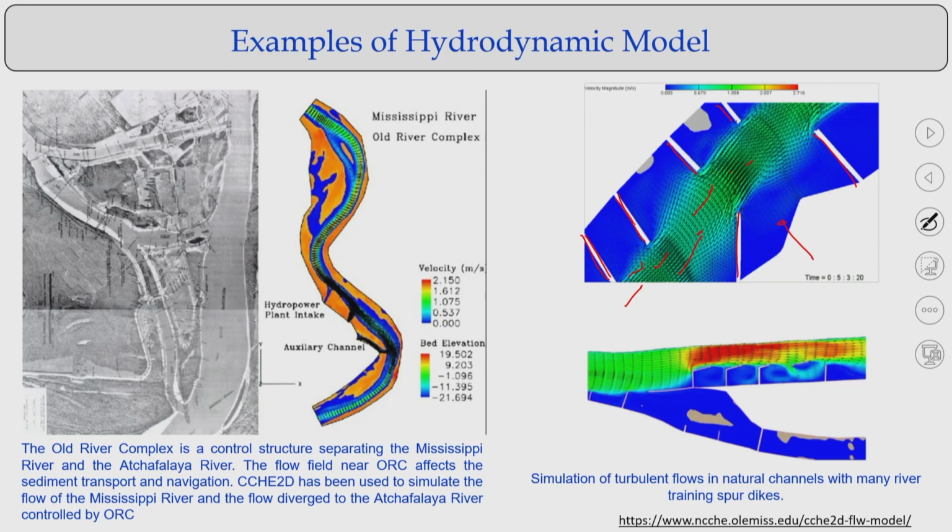There are the spurs, and these spurs confine the river to a smaller width as well as protect the banks. And if you look at these figures with channel bifurcation, there is a series of spur structures, and because of the presence of these structures you can see this higher velocity zone and this lower velocity zone.